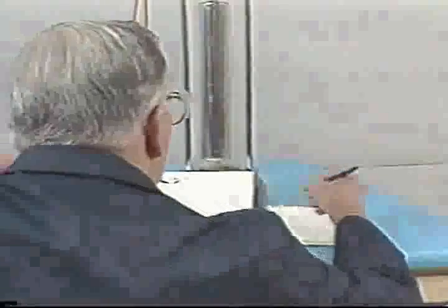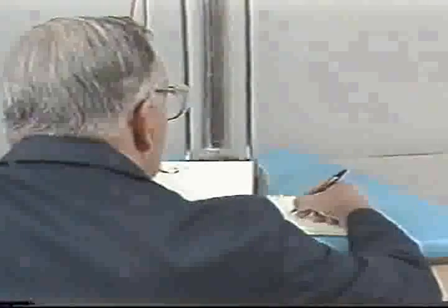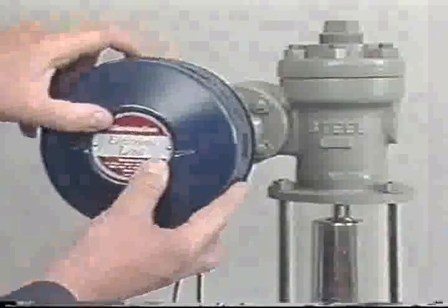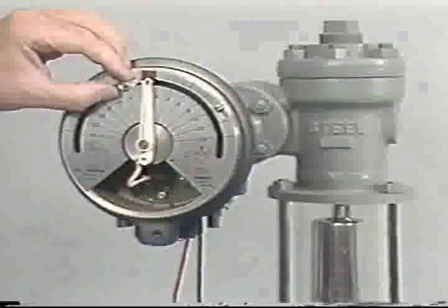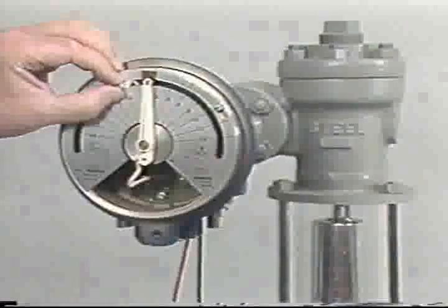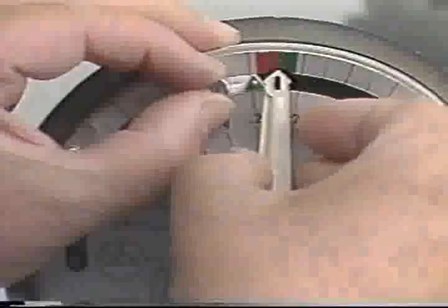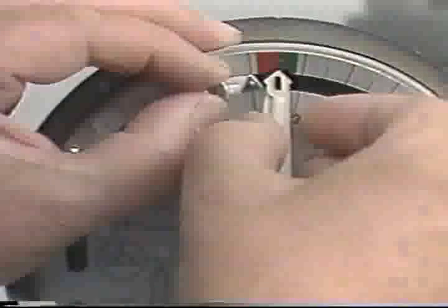Manufacturers typically provide a correction factor to compensate for manufacturing tolerances of the torque tube and the specific gravity of the displacer. The calibration plate is then set using this value. To determine the setting for the calibration dial, multiply the specific gravity of the liquid by the correction factor. Then set the pointer to the compensated value.